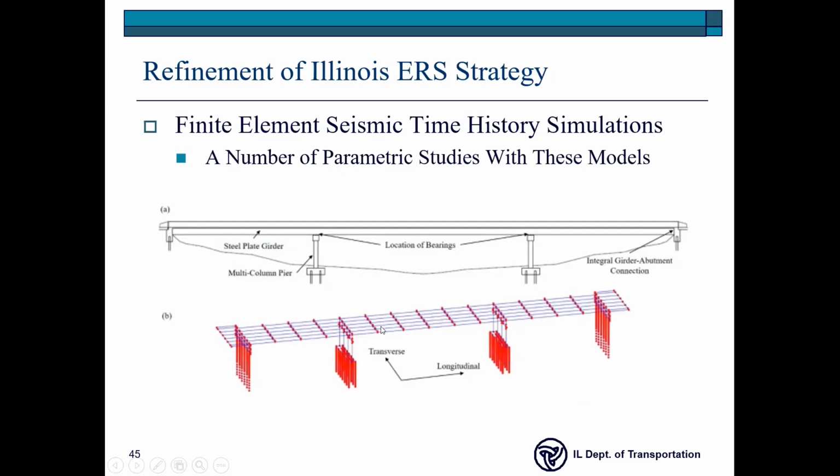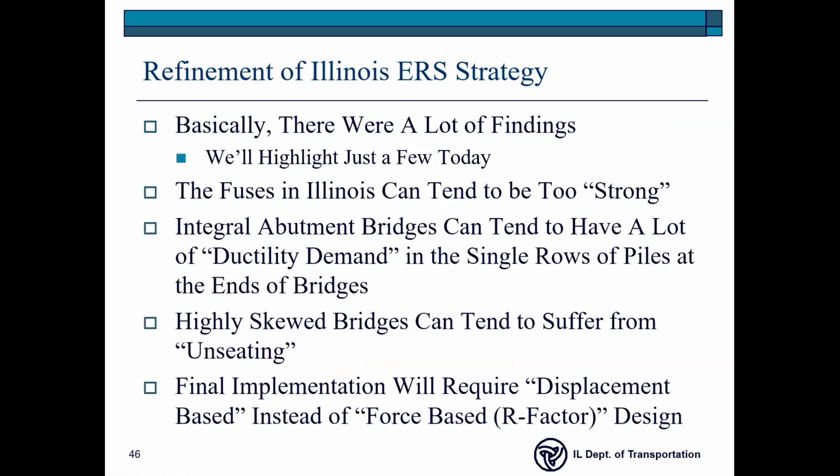computer bridges, finite element model bridges, to these design accelerations and saw how they behaved, and did a bunch of parametric studies, all that sort of stuff, right? And we learned a whole bunch of stuff, and I'll just talk about a couple things today, okay? We learned that our fuses can be a little bit too strong. They don't break up as quick as we want.